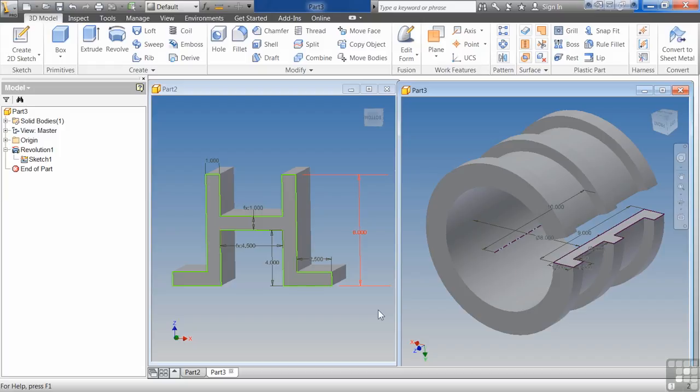The definition of a sketched feature from Autodesk is: sketch features are 3D features that you create from an existing 2D sketch. These features serve as the basis for most of your designs. When you create a sketch feature, you begin by first creating the sketch profile for the 3D feature. For simple sketch features, this profile usually represents a 2D section of the 3D part being created. For more complex sketch features, multiple sketches can be created and used within one sketch feature.